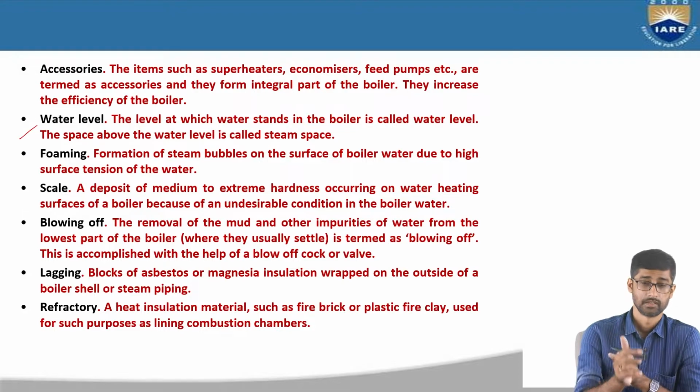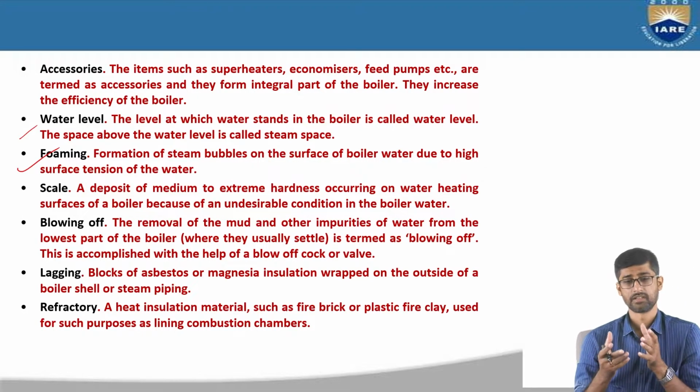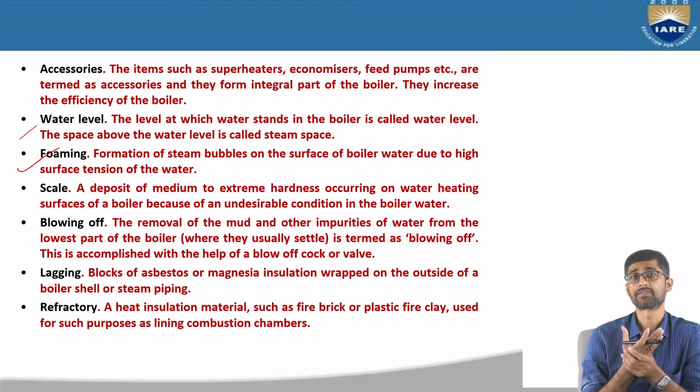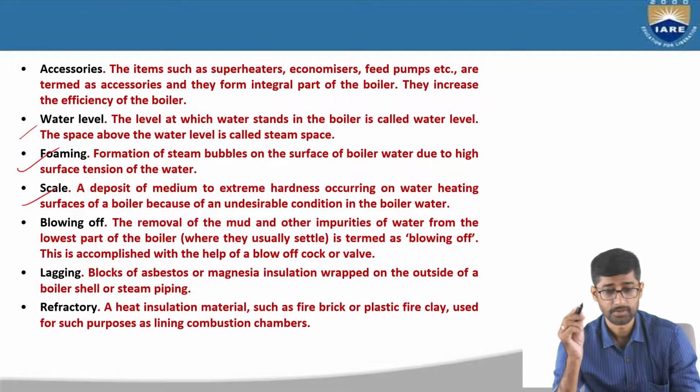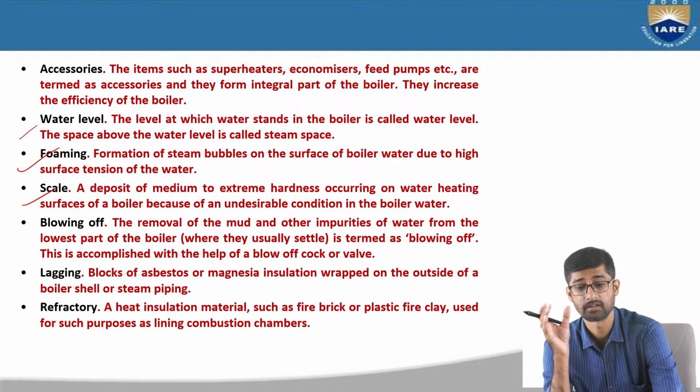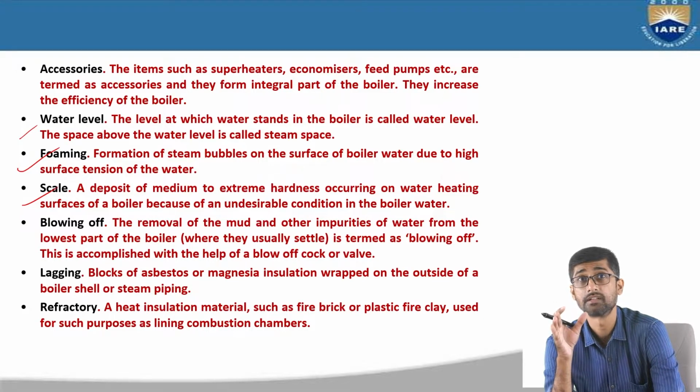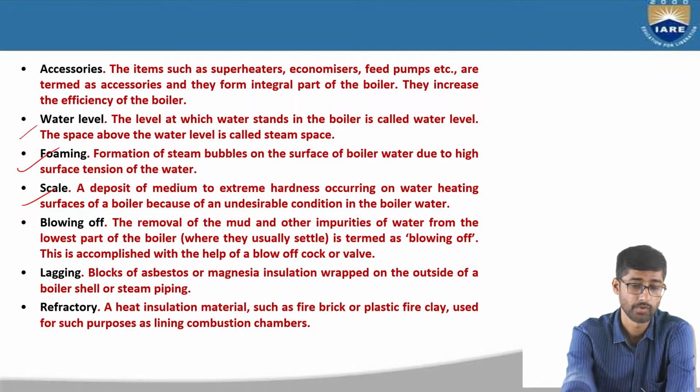Foaming. Foaming is the formation of steam bubbles on the surface of the boiler water due to the high surface tension of the water. Scale. A deposit of medium to extreme hardness occurring on the water heating surfaces of a boiler because of undesirable conditions in the boiler water.